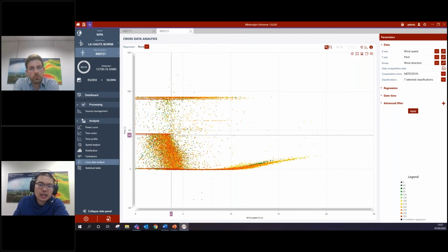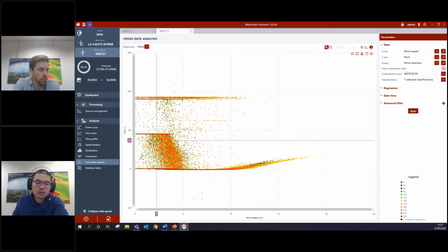So by giving a quasi stop here at 45, with the help of this control strategy, the manufacturer can optimize the use of the motor of the pitch. There is less rotation.